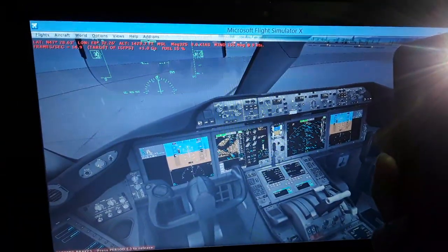It's going to calculate the runway length, the runway slope, the wind direction and speed, the barometric pressure, the density of the air, the temperature of the air. Also the runway conditions, if we decide dry or wet, it is going to give us the takeoff speeds V1, V-rotate and V2 automatically. So we're going to have a V-rotate of 130 knots, a V2 of about 140 knots.